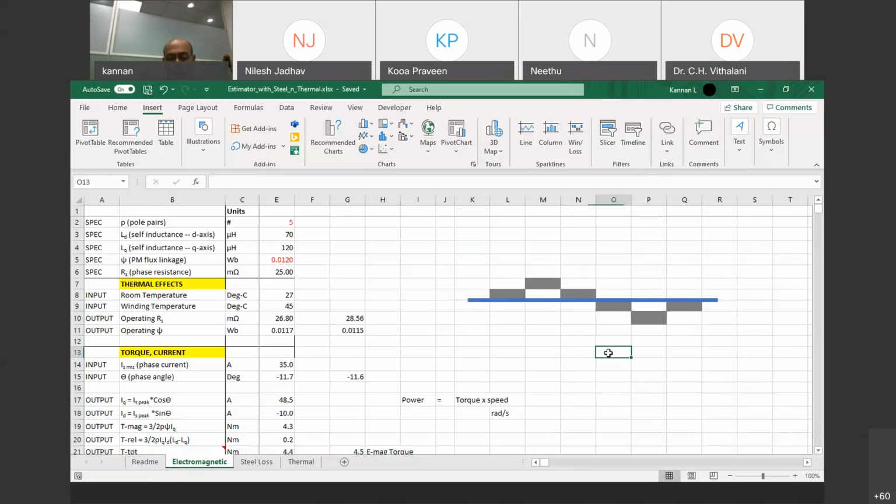Anyway, so this way of making the motor run by mechanically rotating its shaft and then capturing the waveform that's coming on an oscilloscope will tell us what is called the back EMF. This shape is called the back EMF profile of the motor.